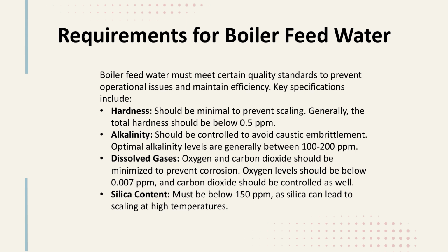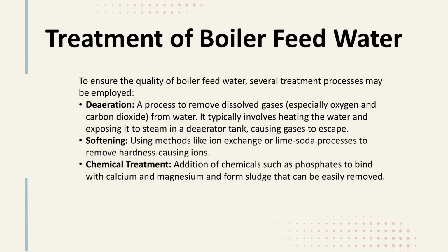These strict standards help maintain the efficiency and longevity of boiler systems, preventing costly downtime and repairs. To ensure that boiler feed water meets these standards, several treatment processes are employed. Deaeration. This process removes dissolved gases, particularly oxygen and carbon dioxide, from water. Deaeration typically involves heating water and exposing it to steam, which forces the gases out.